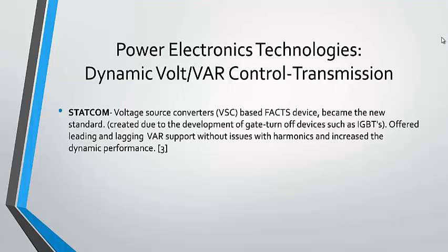STATCOM, Voltage Source Converter, or VSC-based FACTS devices, became the new standard over SVCs, which were static VAR compensators. They were created due to the development of gate turn-off devices such as IGBTs, offered leading and lagging VAR support without issues with harmonics, and increased the dynamic performance.